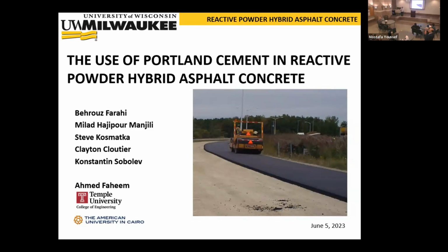Maybe cement is just not the right thing to use actually, because in the end, this is any powder. Any powder has a large amount of chemistry at the surface. I don't know the density of OH groups at the surface of C2S or C3S, but maybe you have silica. In silica, you can go from 3 to 13 OH groups per nanometer squared. If you were to use this higher end of silica, which I don't know where in the world you can find, then you will have a super reactive powder and probably more than cement.